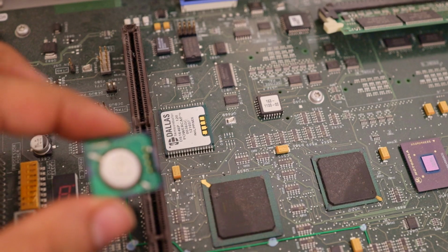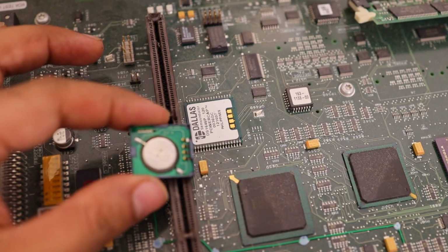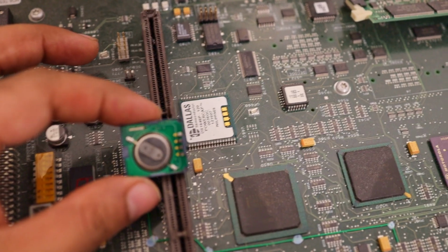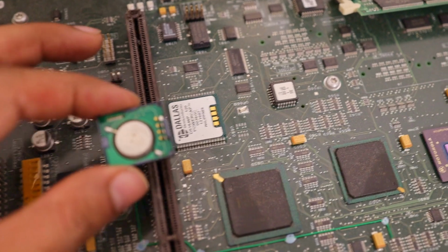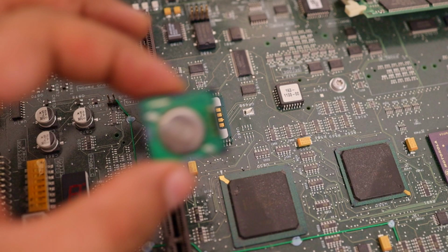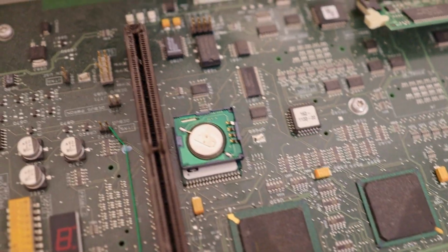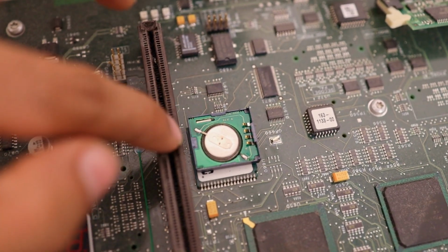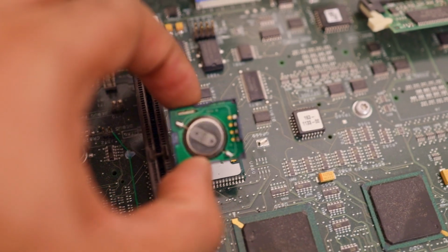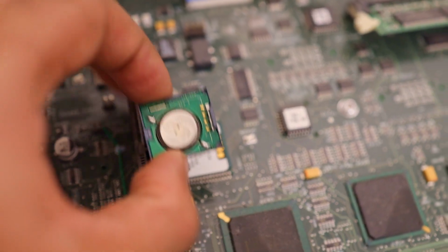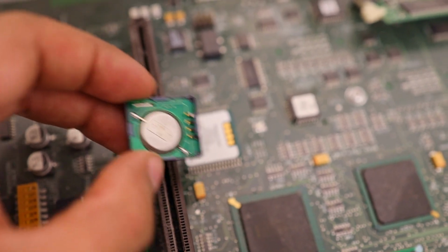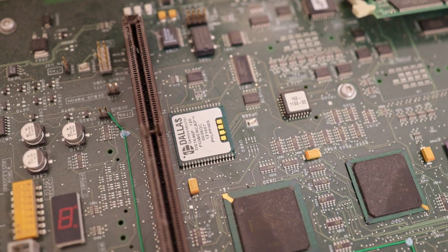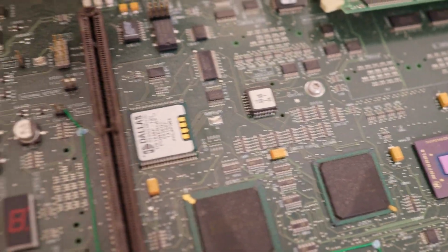As you can see, this module has 4 contacts. Normally, if you find photos on the internet, you will see a power cap module with 2 contacts. It has 4 contacts because it also has a crystal oscillator. You see in the corner this tiny little thing, and it appears to be a special module. We will find out. We will replace this battery first and then try to measure the power consumption of the NVM module. If it consumes too much power, the module needs to be replaced.